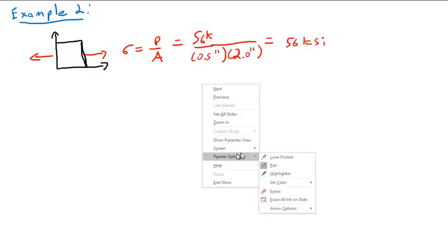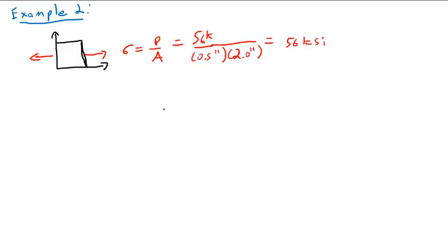However, we wish to find the actual width of the object. So if you imagine rotating through various cut planes, each cut plane will have a slightly different length, and we're going to call that width W. The material thickness is going to be constant because that's not changing as we're rotating. So the 0.5 inches represents the material thickness. This represents the width of the cut plane. And so this is the maximum.